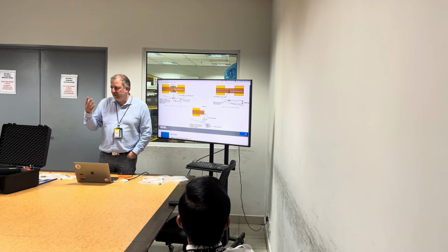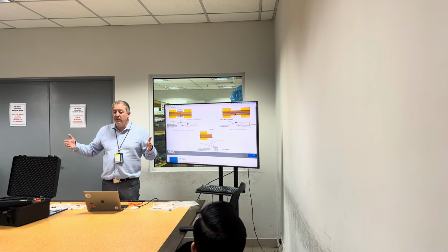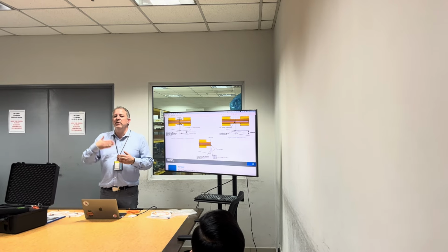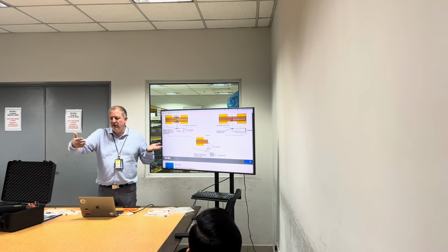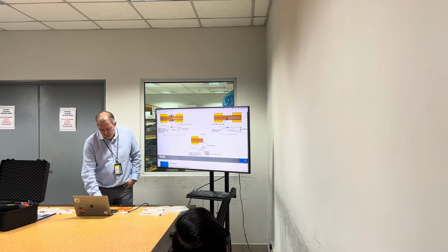So just so you have this in mind, keep in mind the total length of the fiber optics you are checking, and don't get confused by potential peaks that are above the length. Don't take that into consideration in case you see something suspicious.